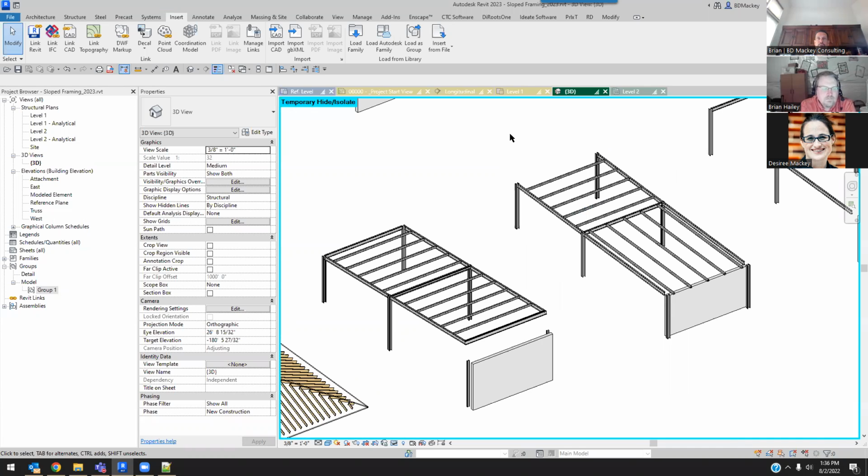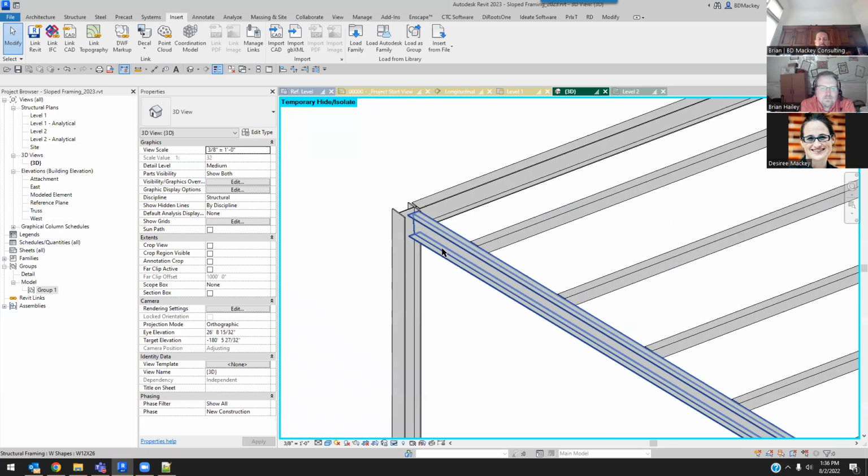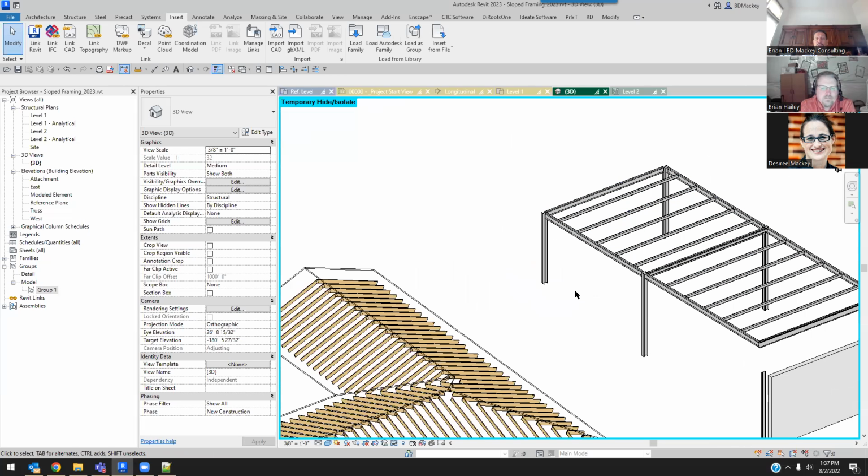Yeah, Sean's like groups suck in structure. Yeah, I'm not a big group person. Like I said, I've created groups of typical framing for this, brought it in as a group, and then ungrouped it. It was just like, man, I got tired of K-series joists. I got tired of this unit we're using K-series joists. I'm going to drop this by 2.5 inches and put the beam system on top. I brought the groups in and then ungrouped them just to get one of them in there, and then I can copy it around. But yeah, just not a big group person in structure.